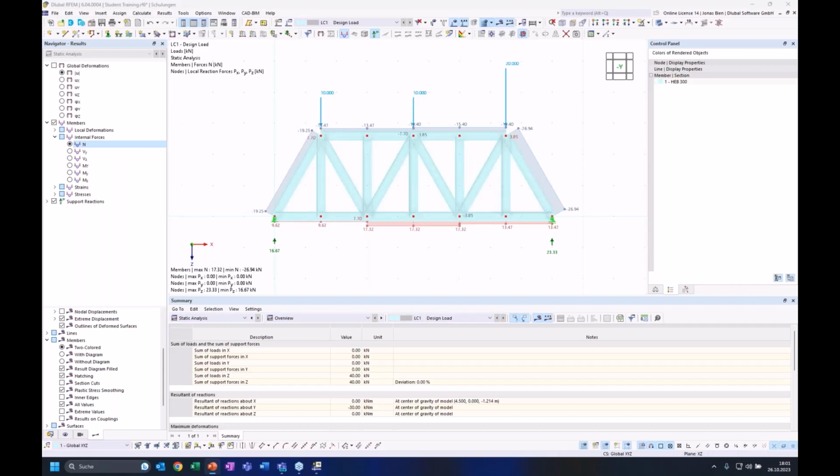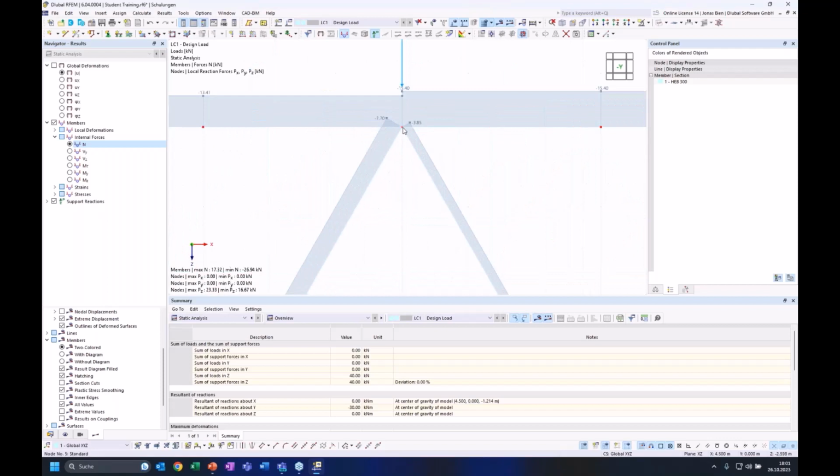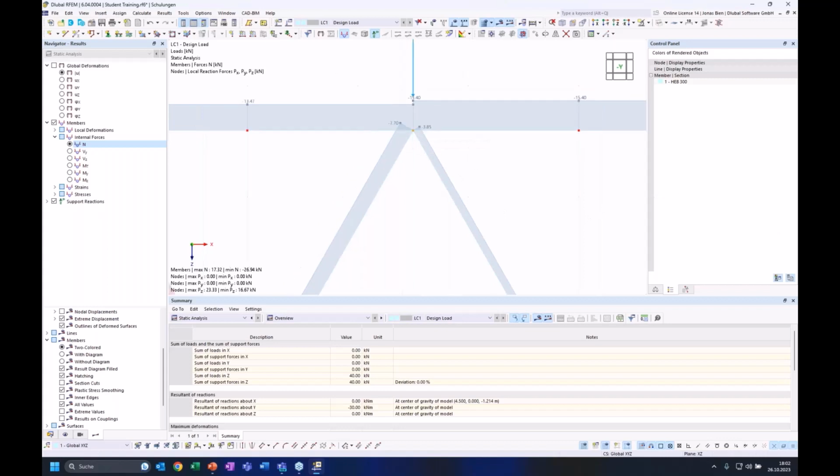joint. Then we have no imperfections in the truss members, so they are perfectly straight and can be considered like this. Another assumption is that we have no eccentricities in the joints, where all the truss members meet. The system lines intersect in one common point. So in this case, here at this node, 5 different members meet exactly in this point. That's also not every time the case in real truss structures.